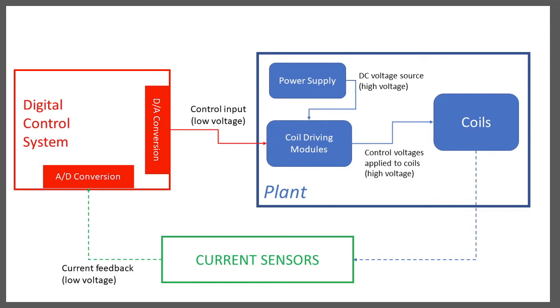Each axis of the Helmholtz coil has three major components. First is the coil driving module, which receives the voltage coming from some input source for probing the dynamic electric current that is passed on to the next component. The second component is the actual coils, which generate the magnetic field.